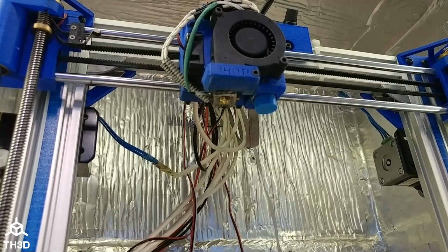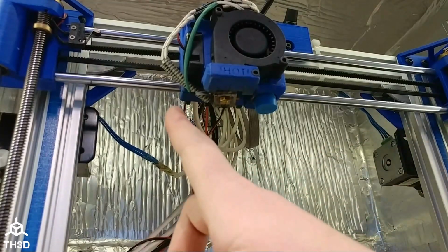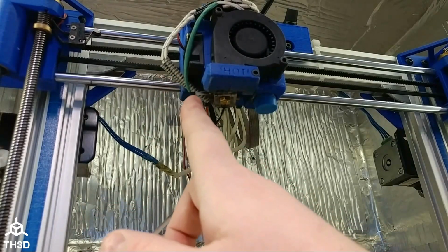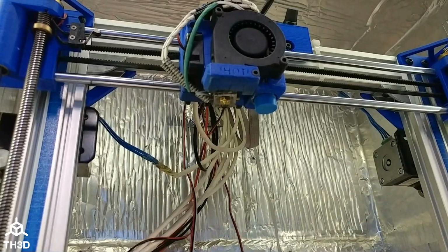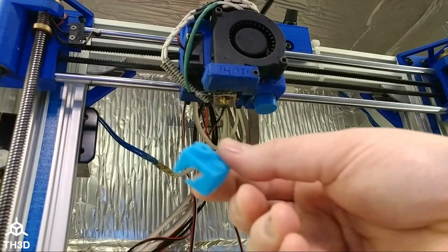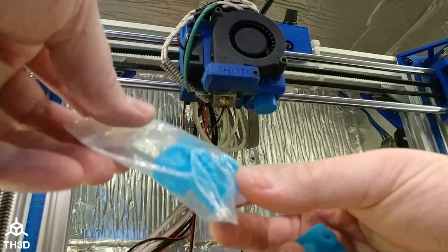Why will your board get fried? Because you're going to send the 12 or 24 volts, whatever's coming in on the heater lines, into your thermistor input and either short to ground or you're going to short to the I/O pin. And the boards don't like that. They'll stop working. So these are the silicone socks we carry.